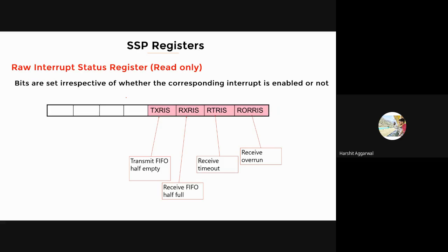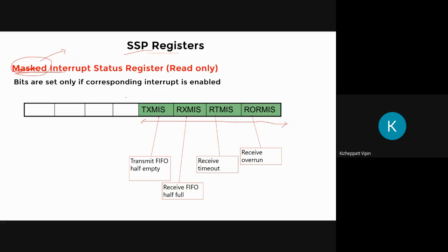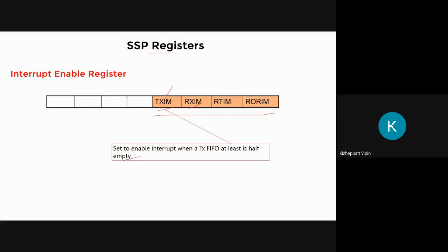So it's not the same as VIC, right? No. In VIC masking is different. Like in our GPIO, if you mask something, you won't get it, right? Yes. Here it is the opposite. So this one, I wrote as interrupt enable register. The actual name of the register is interrupt mask enable register.